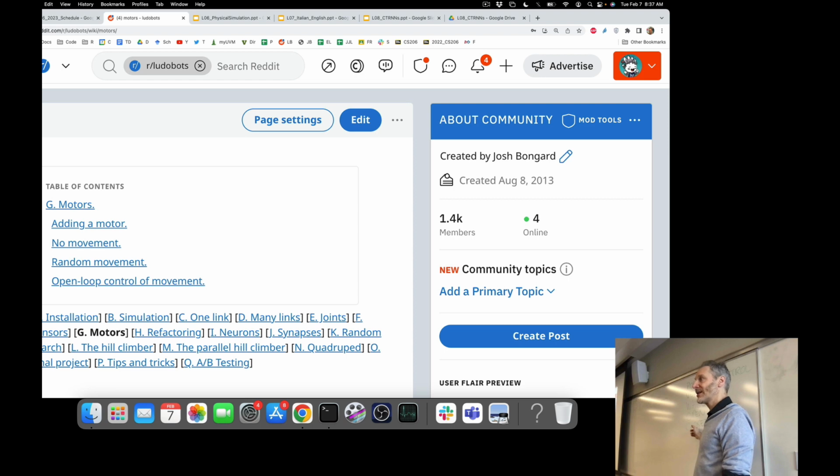For the graduate students that are tackling assignment 7 this week, the moment you add the synapses, you're going to be switching from open loop to closed loop control. Once we connect the sensors to the motors with synapses, and we propagate those values through the neural network, like we talked about in lecture 5, then the values that are arriving at the motors, they're still position control. They're still being interpreted by the motors as desired positions, but those values are being dictated by whatever the current sensor values are, multiplied by the synaptic weights. Make sense? Everybody see the difference there?